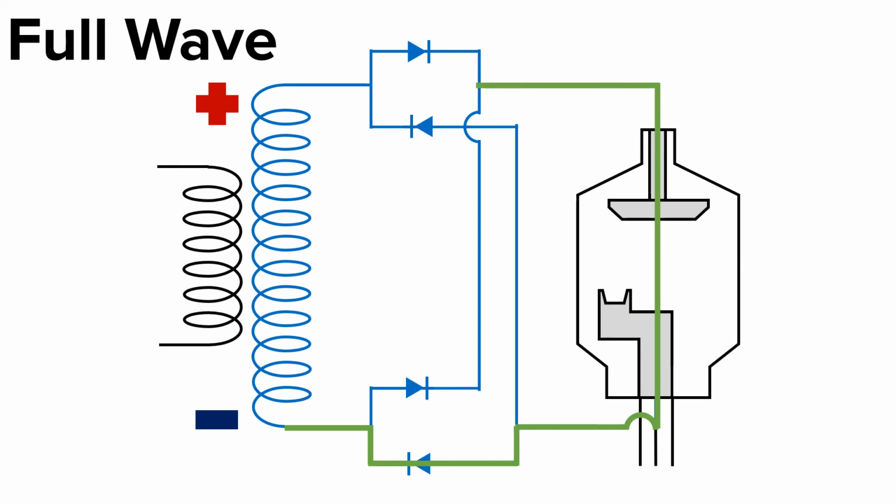At the next break, we have a tough decision, which way to go. If the electrons travel down, they would be able to go through this diode. However, remember the first rule, electrons go from negative to positive. If they took the path traveling down, they'd be going from negative to negative. So the electrons will travel up.